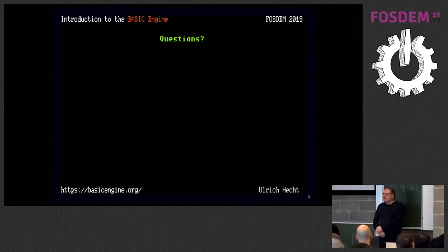So, is flux okay? Yes, you're allowed to use that. There is in fact one guy who uses flux only with HASL boards. I wouldn't rely on that, even I wouldn't. So put a little bit of solder on the pads and that'll do. Anything else? Yes. Did you write an emulator for the machine as well?